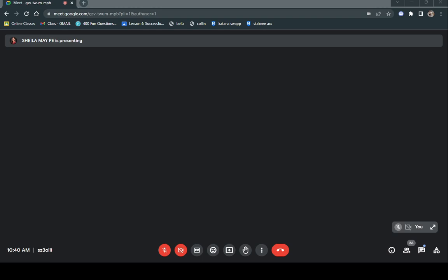Okay, let me explain. Here we have a picture that can help me explain to you. There is no channel here yet, right? There is no channel yet for the e-MOSFET. Now, if we apply a positive potential for our VDS, which is the standard, and we apply a positive potential for our VGS, positive potential meaning any number above 0.